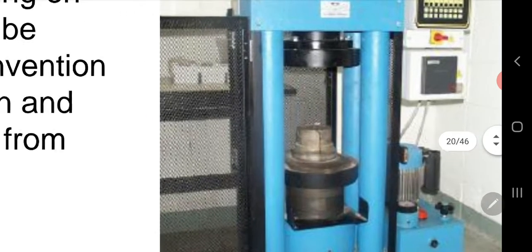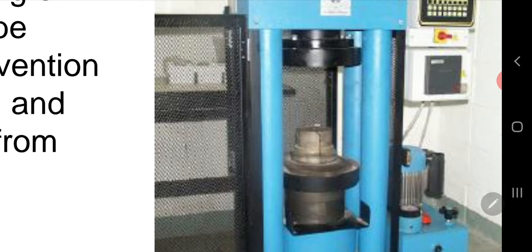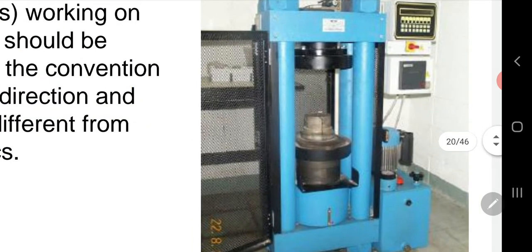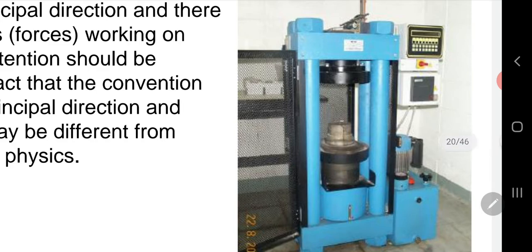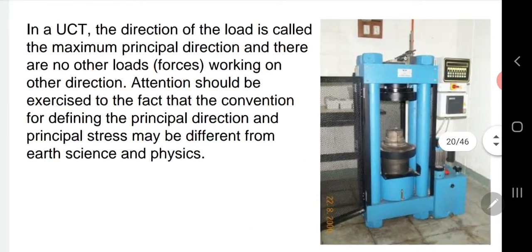If you can see the top of the compressive, this one is cylinder, so it can put uniform load on the top of your sample. This is more complicated compared with your point load test, and all of these are connected to mechanical items and also electrical items. So at the end of the day, when you have compressed your sample and your sample has reached the failure point, it can give the value that you need.